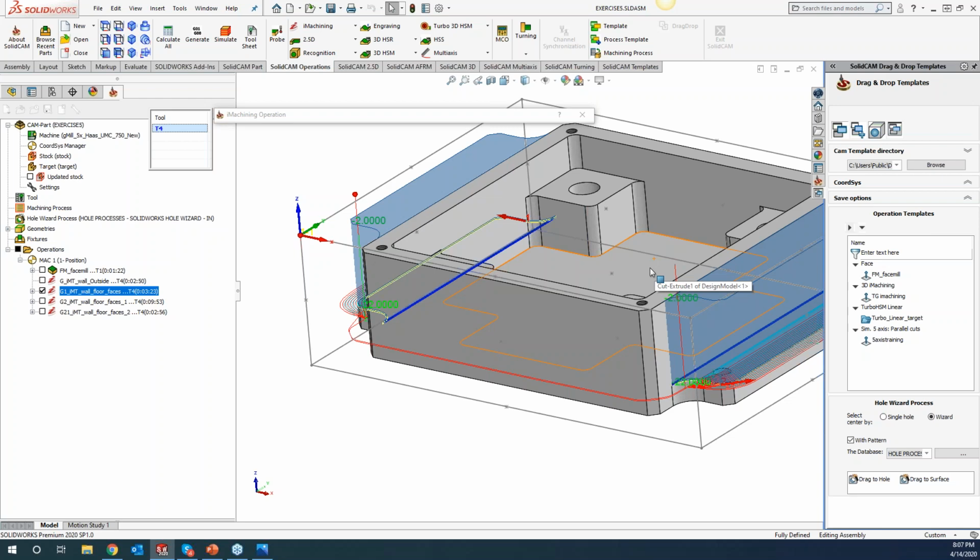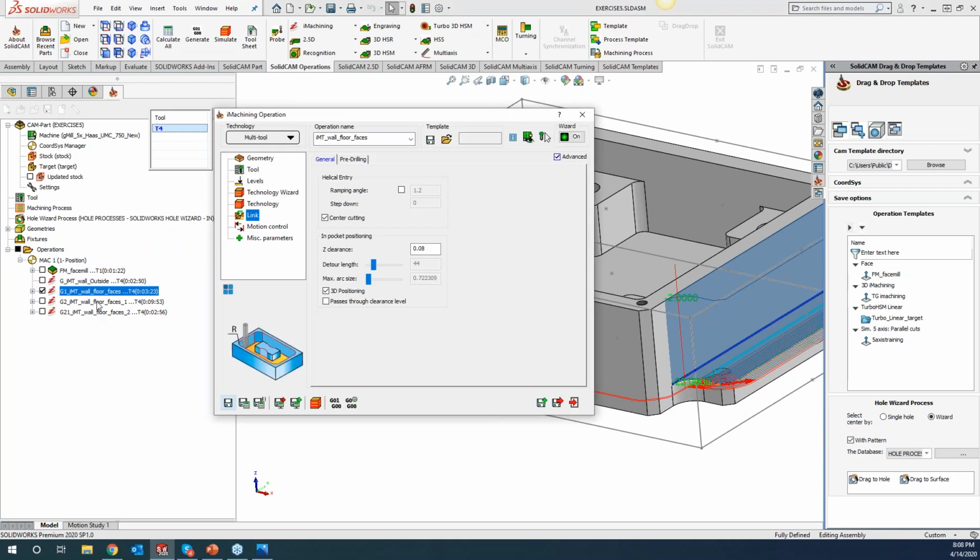So this is completely up to you guys, but it's a great new feature, especially when you're doing roughing and finishing all with the same tool. It eliminates a lot of that retract and keeps the tool staying in place. So we'll do roughing, finishing, and come over here, do a roughing and finishing that way. So let's take a peek at this operation.